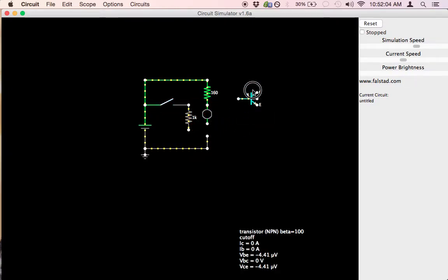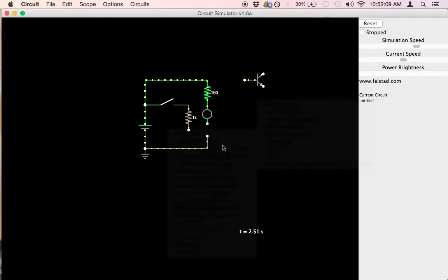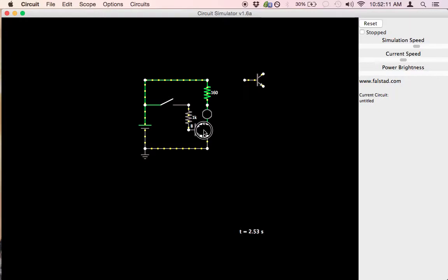What we're going to do is remove this transistor and put in a PNP type transistor. Now in a PNP transistor, things are really different. We have the arrow pointing in the other direction, and in this diagram, the emitter is on the top. Now they can be drawn either way, but it's more convenient for the emitter to be labeled on the top because of the way that these switches are used in a common emitter configuration. Now the situation here is very similar but different. Let me rearrange things so you can understand.